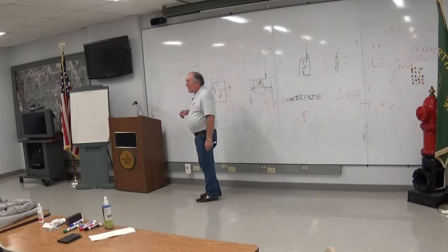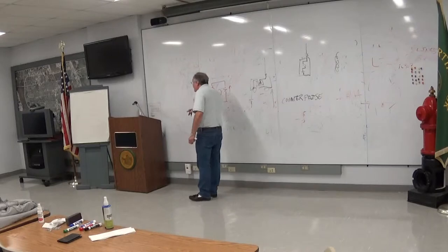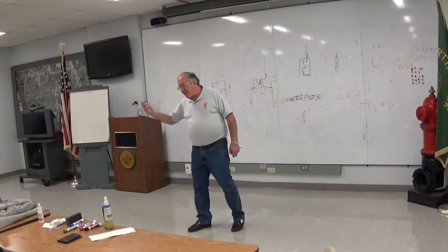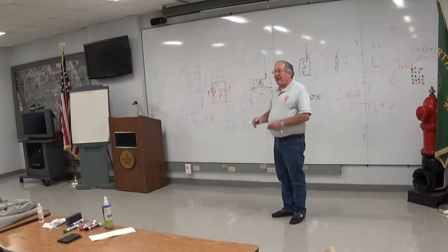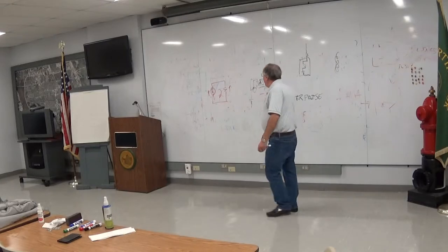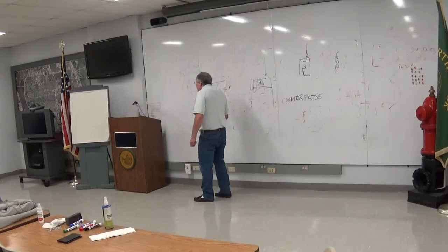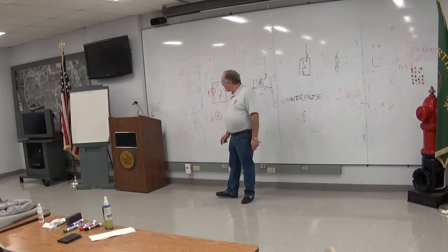if you have a battery or generator or something, it's got some kind of internal resistance in it. Why? Because there's a chemistry inside the battery, and when the current flows through it, there's some impedance from the makeup of that electrolyte inside the battery and the interaction with the poles. Or if you had an AC generator, it's got windings made of metal. They're usually copper. They have resistance.